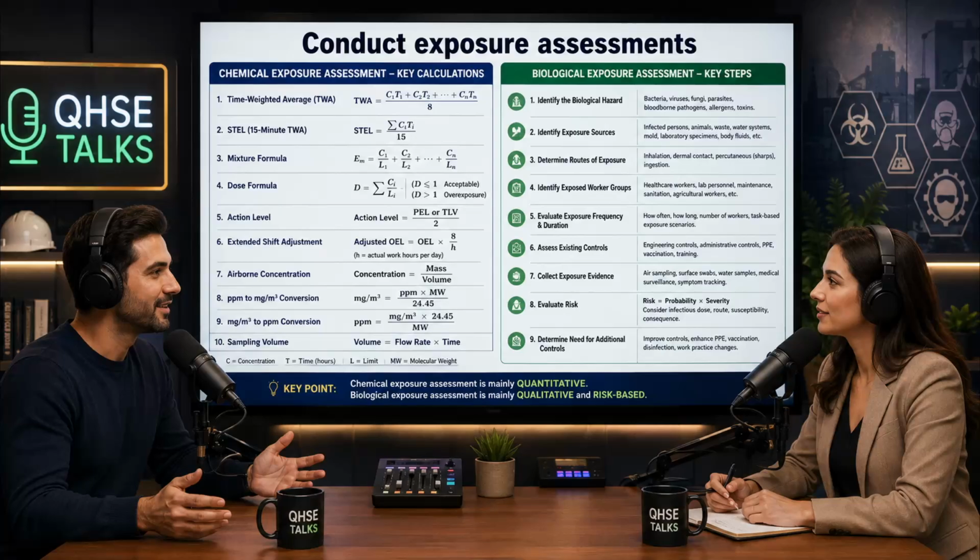No, absolutely not. Not under any professional interpretation. The 30-minute window is purely a physiological safety margin built into the toxicology calculations. It is a buffer for catastrophic failure. So it's not a timer for finishing a job. The operational reality is that the very second an environment hits an IDLH state, the goal is instantaneous evacuation. Drop everything and run. Got it.